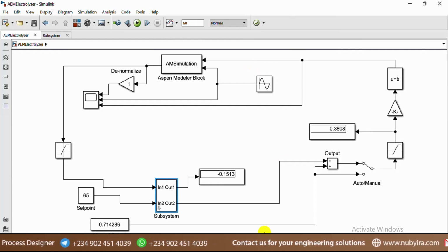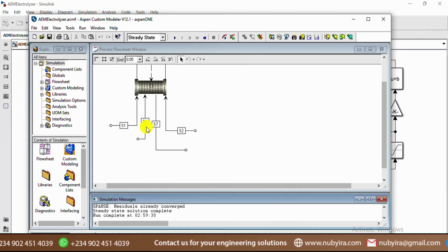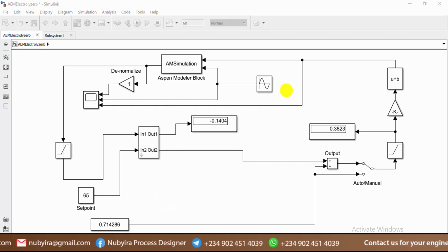I mean, the variable that we are going to be adjusting, you can make it in the form of the temperature of the coolant. Maybe you fix the flow, then you adjust the temperature of the coolant, so you are going to have a faster response for that too. And there are a lot of things that can be done to make the system better than it is now.